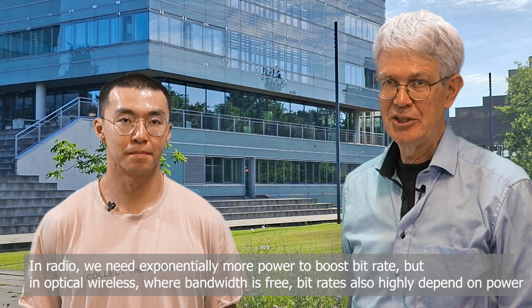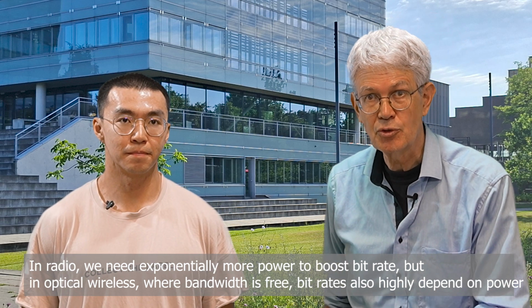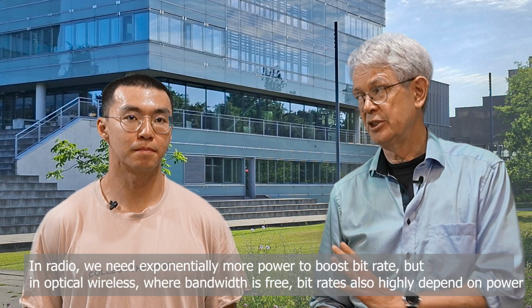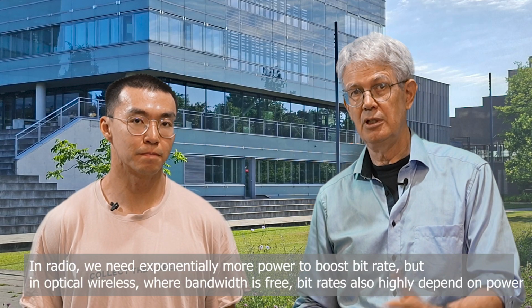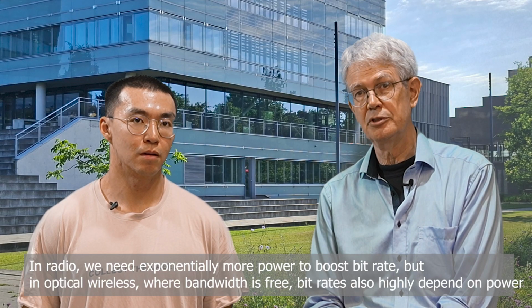As always, we like to boost the throughput of optical wireless communication, or at least to get the highest throughput within the power budget that we have. Xiaochen, that is a topic that you have been studying. Yes. Can we just use throughput is proportional to the bandwidth times the logarithm of 1 plus signal to noise